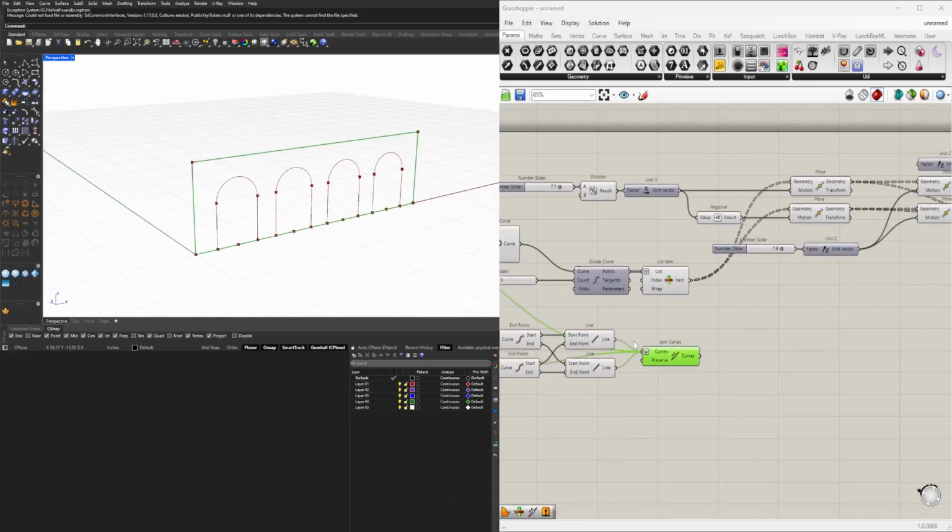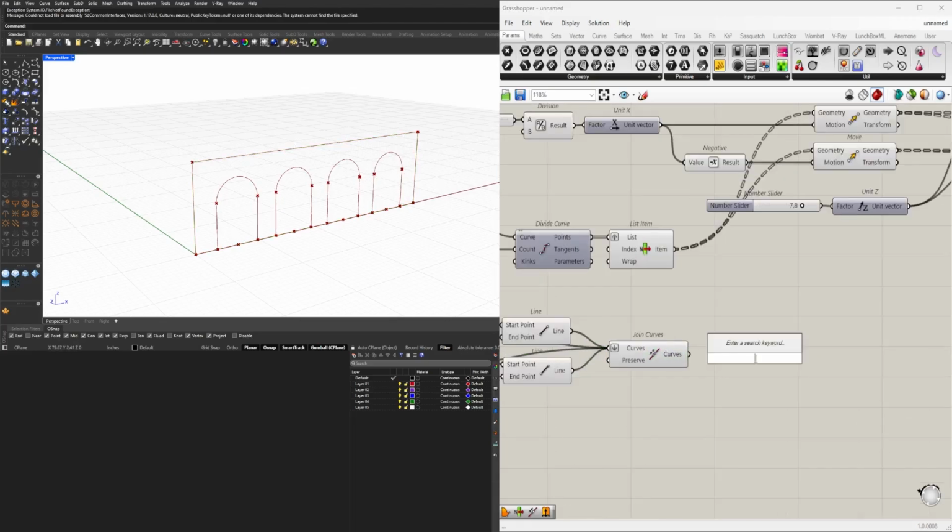All right. So we've got this line segment, which is a closed polyline, and all of these which are closed polylines. So what we need to do is use a component called region difference. The reason why I like to use region difference is because you can get the same results that you can get with Boolean difference or Boolean intersection using region difference or region intersection, and it won't be as computationally intensive as it would be if you do a Boolean difference.